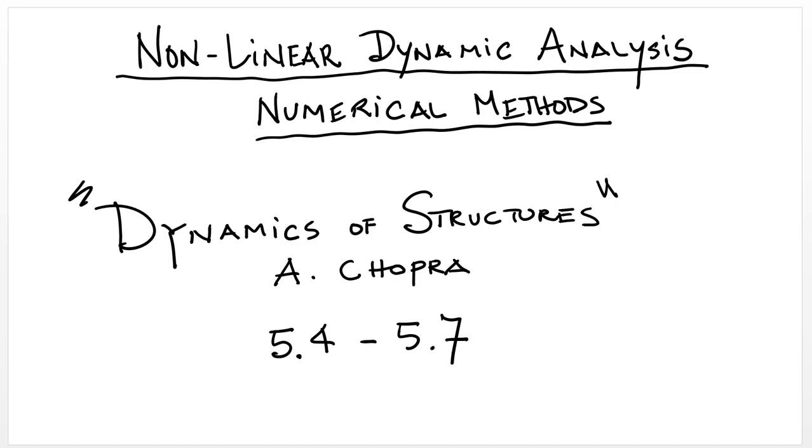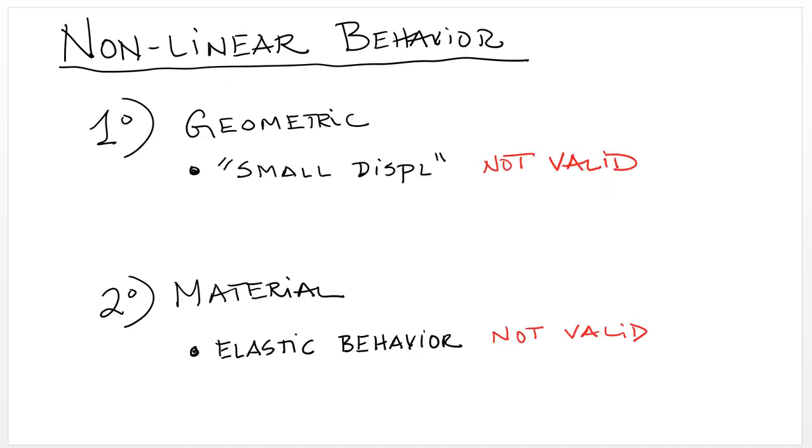In this lecture, we're going to discuss nonlinear dynamic analysis using numerical methods. We're basically going to follow the same notation and formulas presented in sections 5.4 through 5.7 of Professor Chopra's book, Dynamics of Structures. There are basically two general classes of nonlinear behavior in structures.